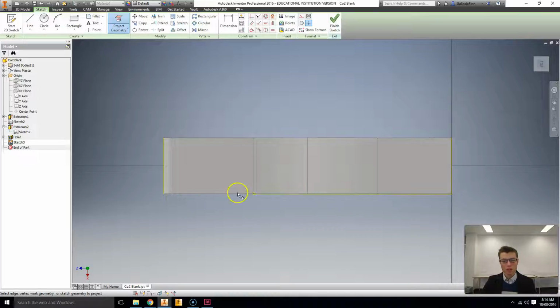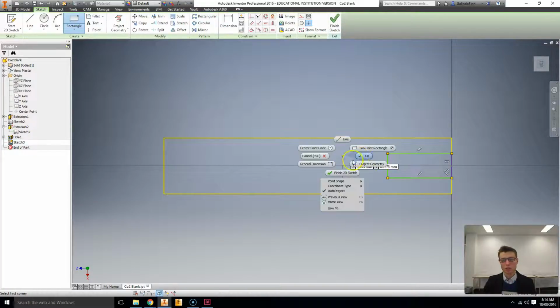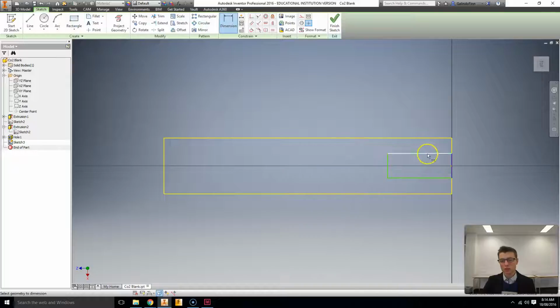Now once I've done that, this will enable me to see the outside profile I can use, and I'm going to click the Cut to Slice Graphics button. You can see this is the profile we've got. Now I need to keep quite a lot of my rectangle space at the back here, so for my CO2 Dragster cartridge. So I'm just going to create a rectangle that matches the size.